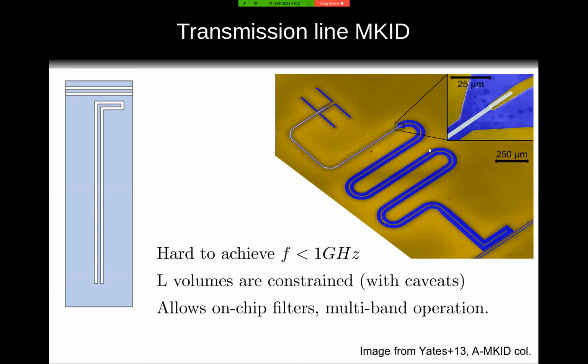But the geometry of that transmission line is the thing that defines your L and your C, and therefore your resonant frequency. The photons are getting absorbed at the upper left there, and the connection to your electronics is on the bottom right. So the L in the top left is higher, and the C in the bottom right is higher. But they're matched impedance wise.